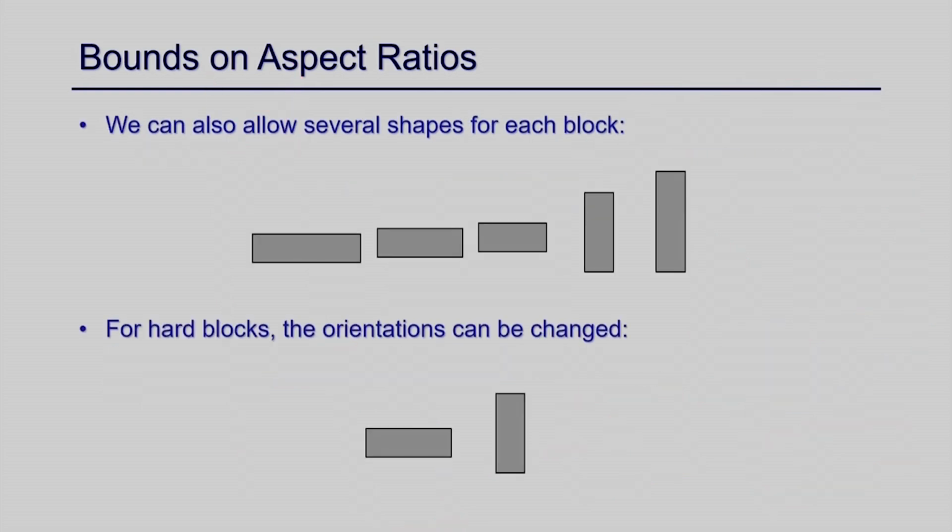As I mentioned, for the same size you can generate different kinds of blocks, and the orientation may be this way or that way. So you have to consider all possible such orientations given the aspect ratio constraint, and then try to place all those blocks in the area. The primary objective is to reduce the area size, so that you can place all of them in the smallest possible area. This is what floor planning is.